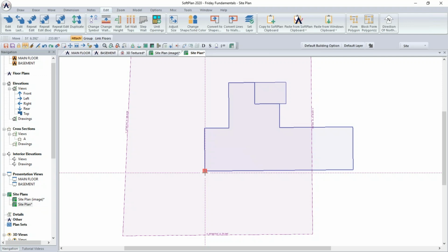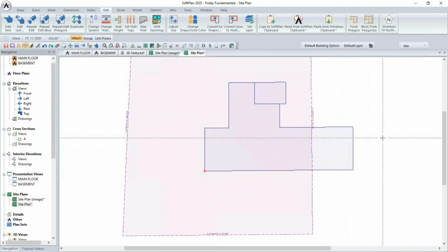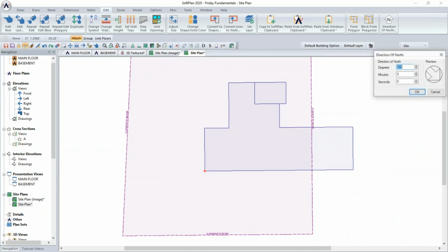That's the direction of the actual floor plans, and I want the house to be in that same orthographic. To do so, I'm going to come back to my north options, and I'm going to need to change the direction of north such that the angle of the building outline and the front of the lot are in the same direction, or 90 degrees to the screen.